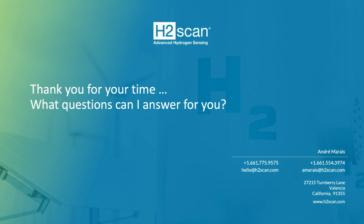That's the first attribute. The second is that you've got to be above what we call our lower detection limit. If it's a very low level we will detect it, but anything below 5 ppm, we don't guarantee the accuracy. But if you're at 10 and you're taking the manual sample from the same place at the same time, there's no reason to expect anything different, and experience has shown us that it's not. That's why our sensors have the optional bleed ports, so that you can take the sample from exactly the same location.